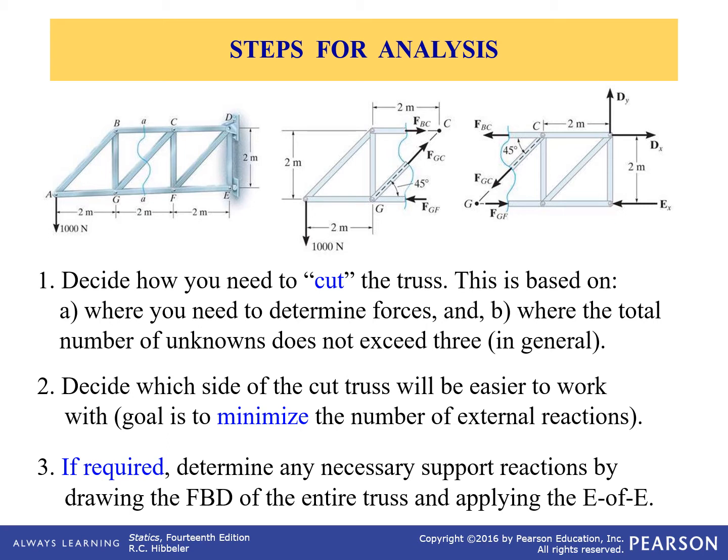Again, you can reason through and figure out which is in tension and which is in compression. Don't waste your time. Just try everything in tension, do the problem, and guess what? Positive answers, it'll be tension. Negative answers, they'll be in compression. So we cut it, we get our two pieces.